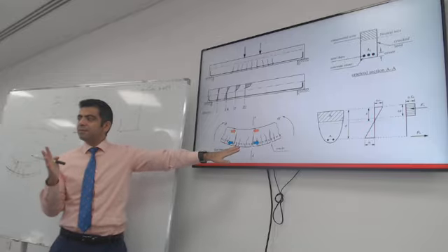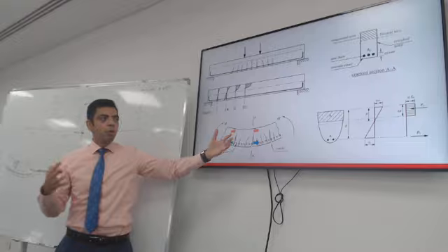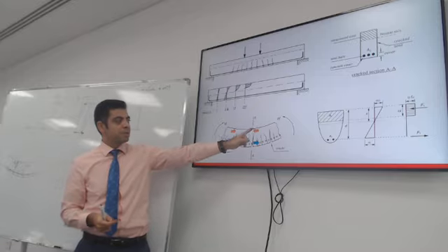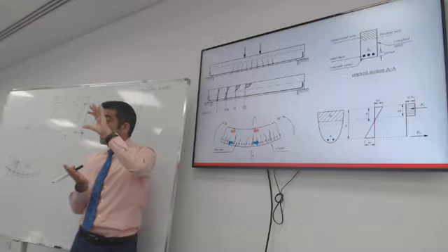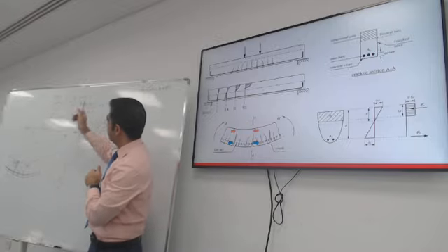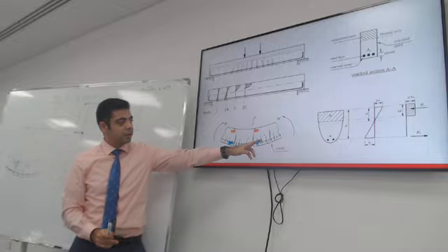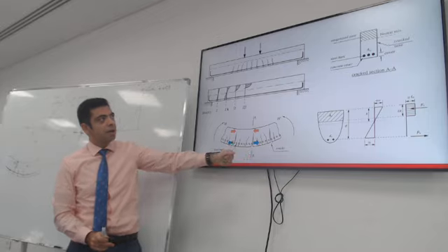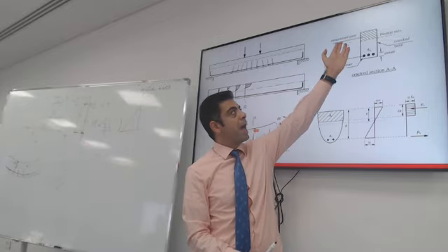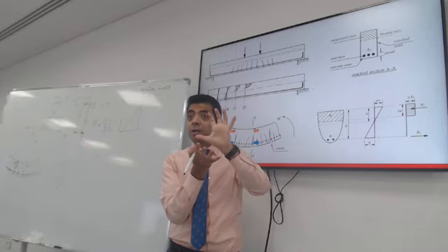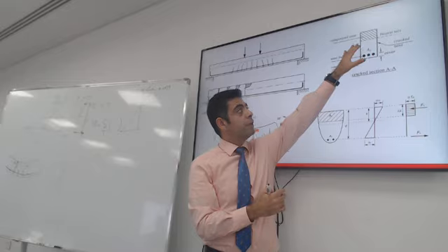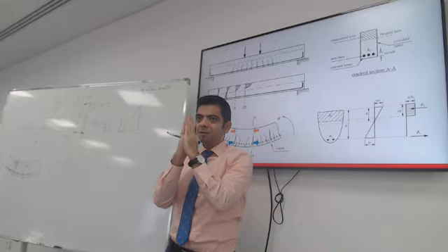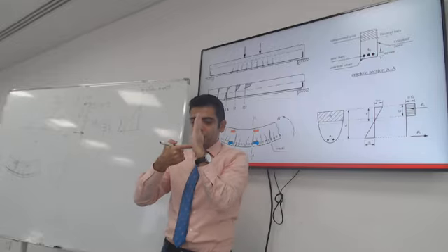This is more or less a cracked section. What are the forces? How are the forces working? There is a compression force resisted by the concrete still intact, and all the tension is resisted by the steel bar. So you take a section here and you try to analyze it. Only the hatched part is intact concrete, capable of taking compression. All the unhatched part is part of the crack, like a void. The two pieces are separated. There's nothing in between, there's just the bar.